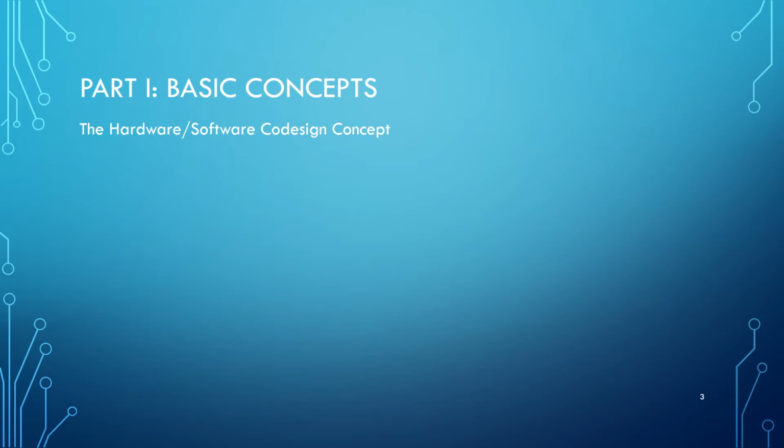In this lecture, the hardware is modeled in single clock synchronous digital circuits, usually in combinational logics and flip-flops. Examples would be registers, adders, and multiplexers. Cycle-based hardware is usually referred to as register transfer level, also known as RTL, because the behavior of the circuit can be thought of as a sequence of transfers between registers with logic and arithmetic operations performed on signals during transfers. The single clock model is a very convenient way.